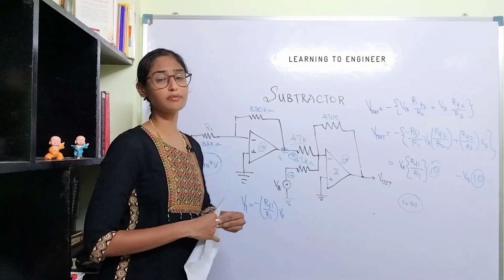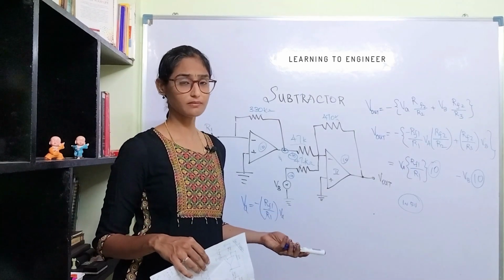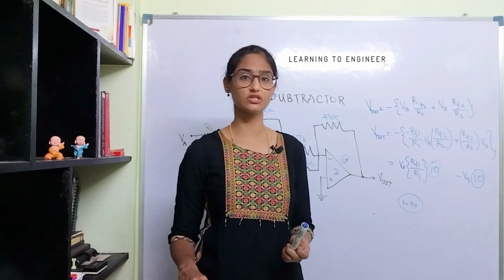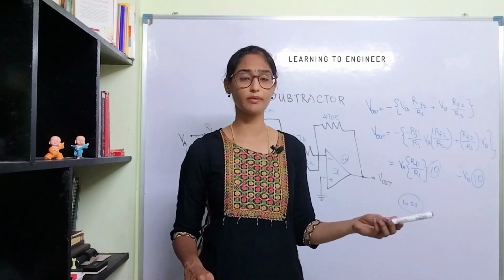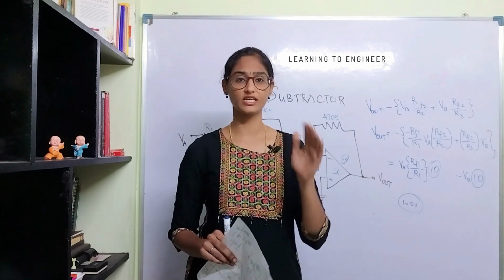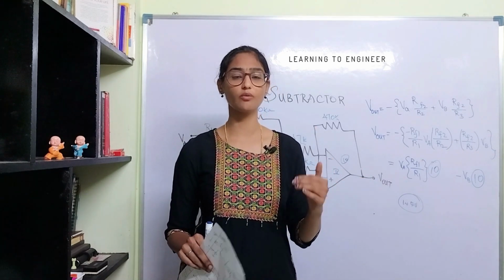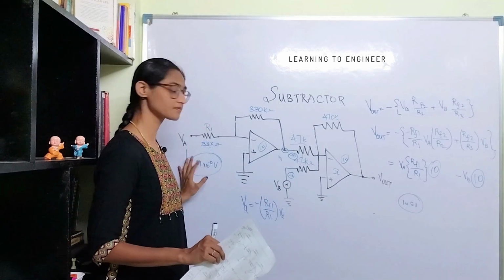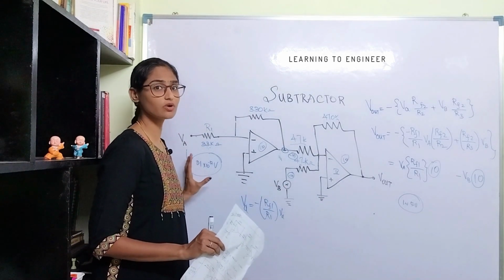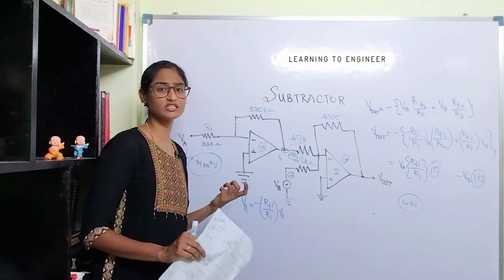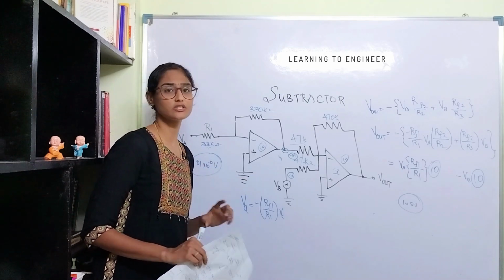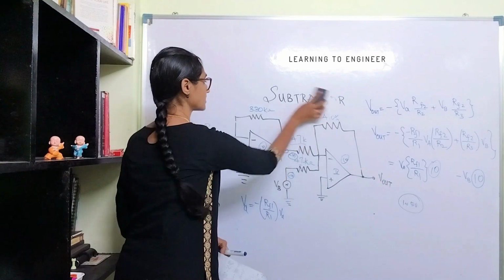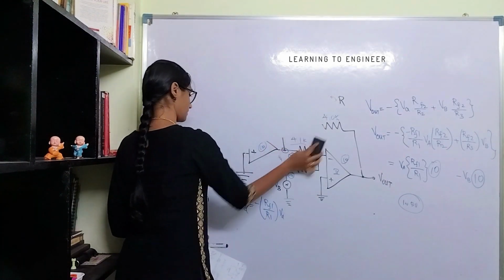Ideally, amplifiers have infinite gain, but practically the circuits are not like that. You can find out the open loop gain of those circuits in the op-amp's data sheet. So the output will be the open loop gain times the input voltage. So this high value cannot be achieved by one single amplifier. So they cascade amplifiers together. This is called a gain multiplier.